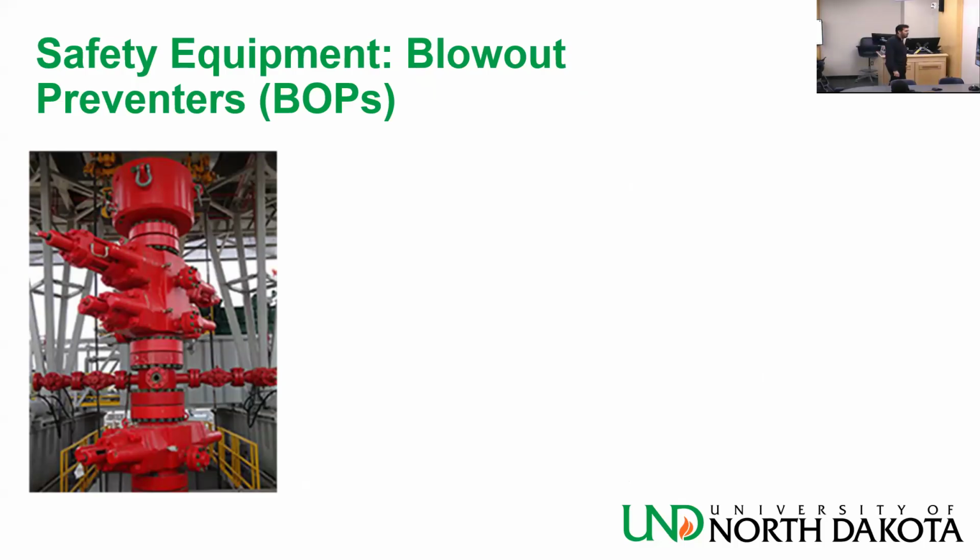Once you become experienced and they take you to a well and you see a BOP that looks like this, you will be able to deduce from the shape that this is basically the annular preventer, or hydril. It's basically a balloon that inflates and covers everything outside of the pipe. This is the one they use more often. If you watch the movie Deepwater Horizon, they show the balloon breaking at some point. Macondo. That is basically the annular preventer. Some people call it the hydril.